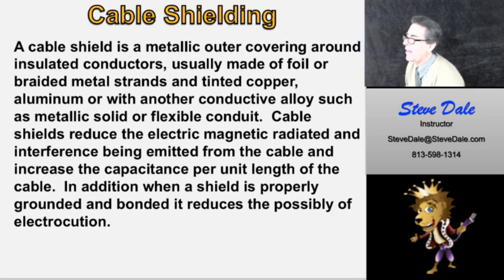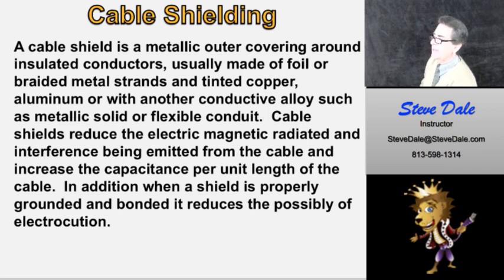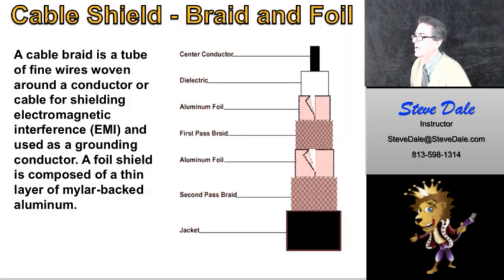A cable shield is a metallic outer covering around insulated conductors, usually made of foil or braided metal strands of tinned copper, aluminum, or another conductive alloy, such as metallic solid or flexible conduit. Cable shields reduce the electromagnetic radiation and interference being emitted from the cables, and increase the capacitance per unit length of the cable. In addition, when a shield is properly grounded and bonded, it reduces the possibility of electrocution.